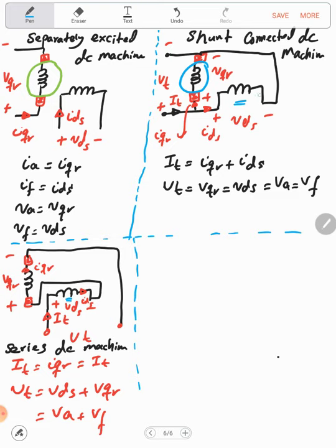in general the resistance is very small, while in the shunt winding the resistance is very high. So simply if you have a machine and you don't know whether the coils or the terminals are series or shunt, simply do the DC test or measure the resistance, and if the resistance is small, then this is the series field, and if the resistance is high, this is the shunt field. So sometimes we can combine the shunt field and the series field in order to achieve extra benefit.